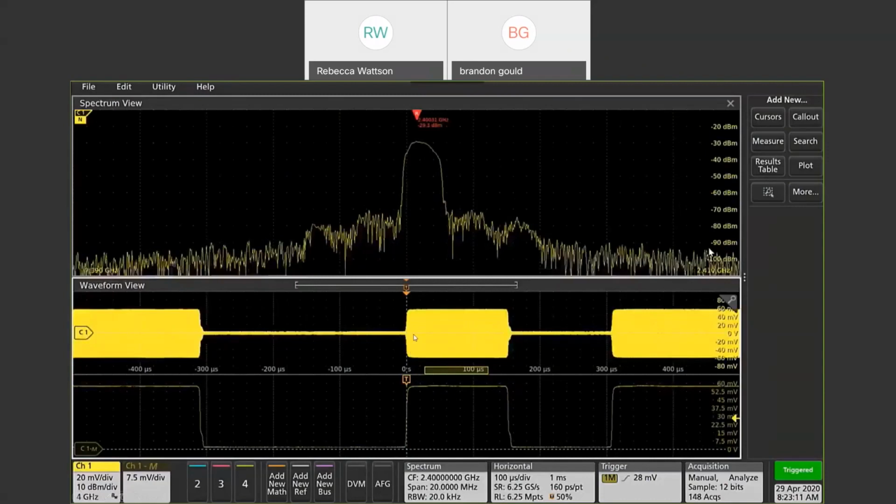So how do I get a burst like this to show up and trigger off of ones and zeros? With a magnitude versus time trace turned on right here, we're able to use the hardware trigger to burst or to trigger on the rising edge here, the pulse width, or the timeout here. So what we have is now the ability to stabilize the signal with triggering capabilities on edges, pulse widths, and timeouts. Really able to demodulate this too. If there's any behavior within this pulse, we'd be able to see fluctuations in either magnitude or frequency with this additional plot here.